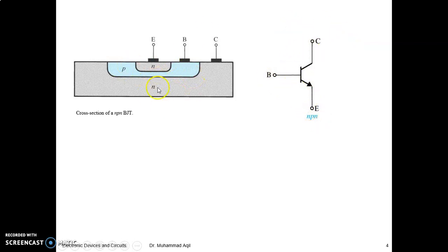And this is the structural difference between emitter, base and collector. The emitter is very short in structure as compared to the collector, but is very heavily doped to emit more majority carriers. The base is thin and lightly doped to have a small base current, and the collector is very huge in area, so that it can collect most of the majority carriers emitted from the emitter, right?